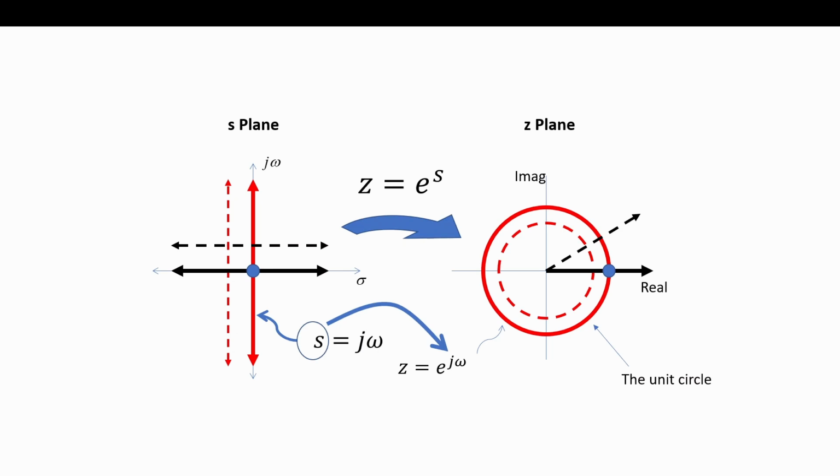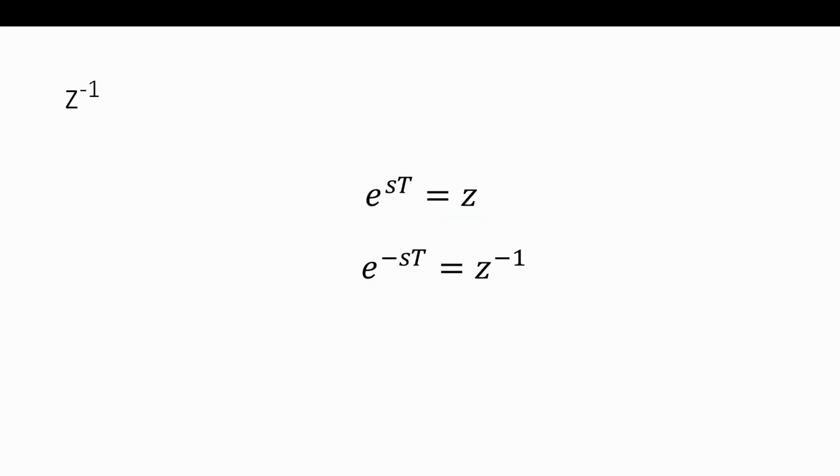So it's, what do you want more? Do you want to match the impulse exactly? That would be something called impulse invariance. Or do you want to match the frequency response exactly? Or do you want to match neither, which is this matched Z transform? Gets you close on both, but they're both in error. So that's a consideration between all the different mappings that exist that we'll touch on.